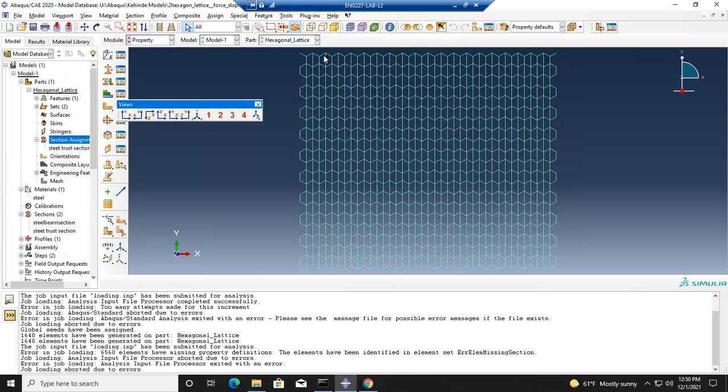You see why? Because this thing is statically determinate, except for these ends are unstable. You can see, right? If you have hinge at this node and this node, then it is unstable, right? It will just collapse, right? Yeah. That's why it could not do it. But if you remove this and this, then there should not be any instability after that. You see what I'm saying?